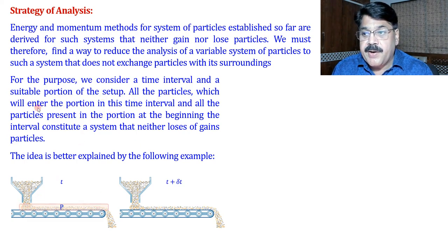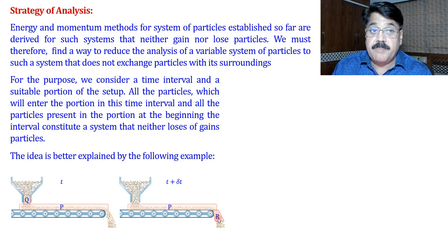Now, all the particles which will enter the portion in this time interval. So we consider all the particles which will enter this portion in this time interval delta t. Suppose here, in this portion Q, all the sand in this portion Q will enter P in this time interval delta t. So all the particles within Q and P will constitute our required system. Why? Because at the end of the time interval, what will happen? This will enter here, and an equal amount of particles will leave here, and they will constitute portion R.